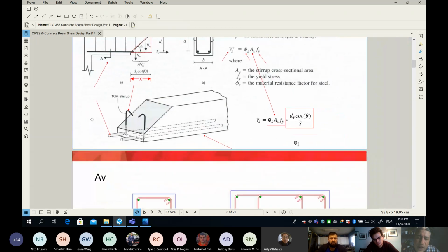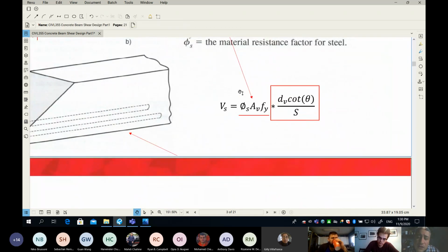And then all you have to do finally is multiply the force that can tear one stirrup by the number of stirrups. Guys, what you see on my screen, there is no super science. It's very, very basic. Do you guys agree or disagree? Agree. Take your time. If you cannot follow, take your time. The V sub s, which is the contribution of the stirrup to the shear, is nothing more than the force that can tear one stirrup, multiplied by how many stirrups go through the shear crack, which comes from the geometry.